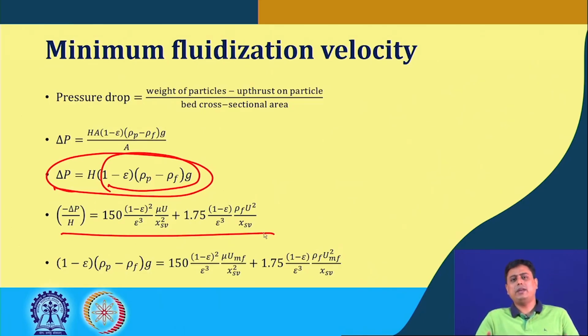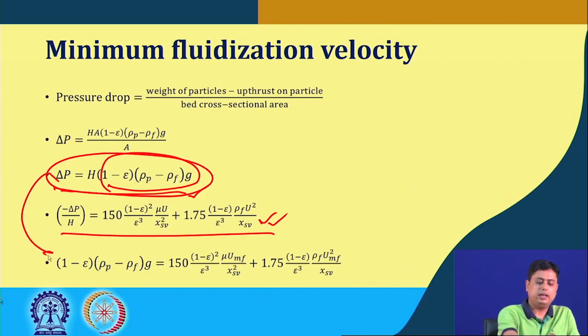You can think of it as a fixed bed structure, but with the maximum porosity. So if we use the Ergun equation until the minimum fluidization velocity, we can replace this del P expression in the fluidized bed at that fluidizing state. So, we have this relation.